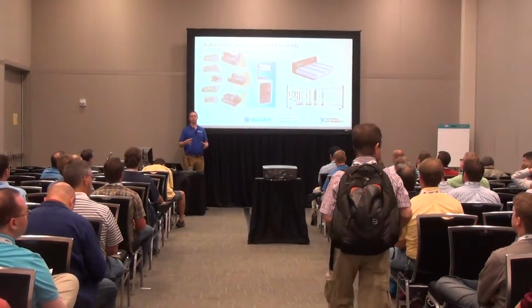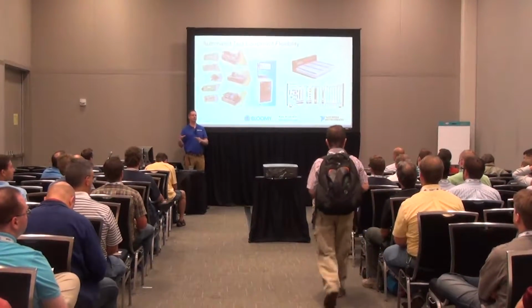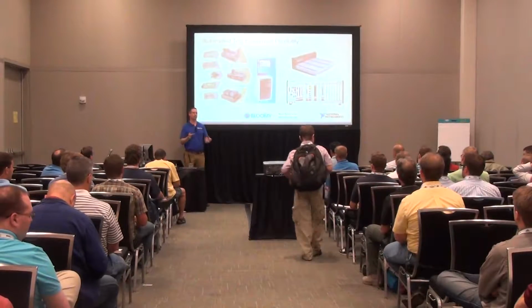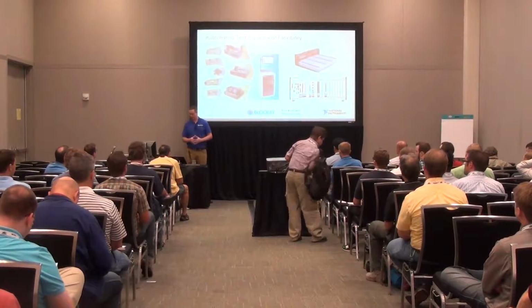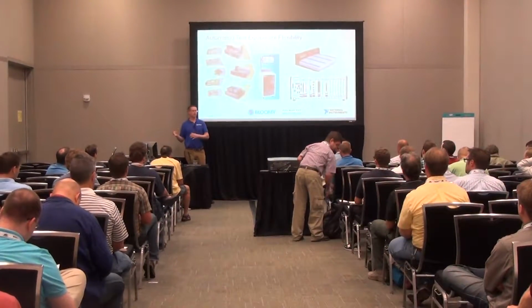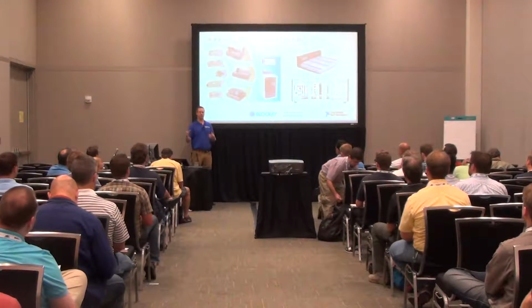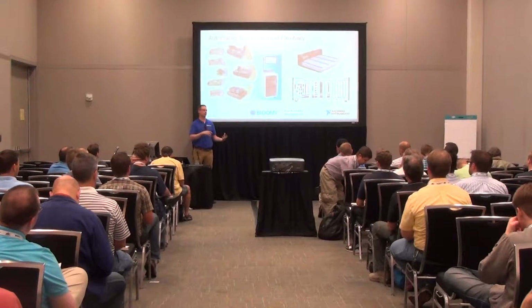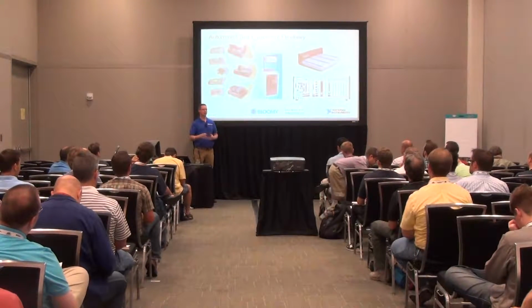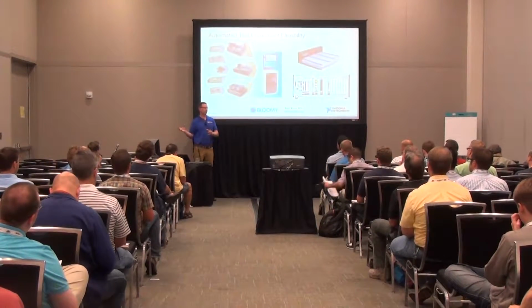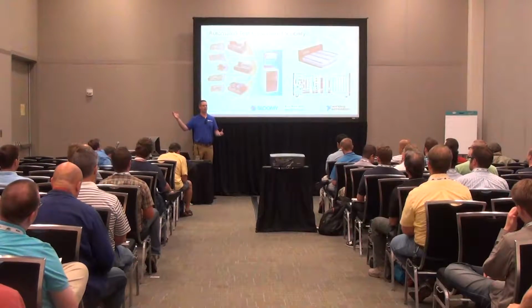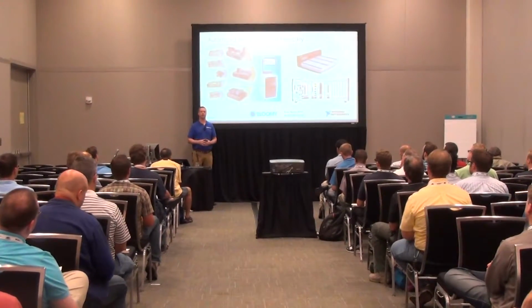And so we use abstraction layers in order to allow the test system software to adapt just as easily as your hardware can adapt. Something as simple as swapping out a power supply, because maybe you had equipment failure, you had to pull something off the shelf, or you have an obsolete instrument, could take dozens to hundreds of hours to update all of your test procedures if you need to rewrite every single driver.